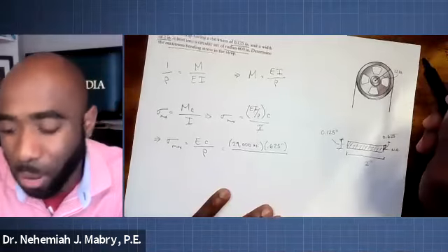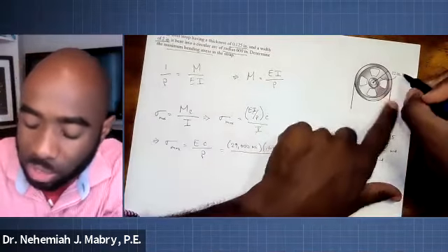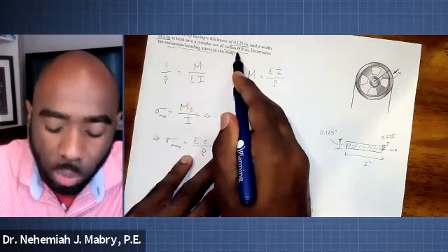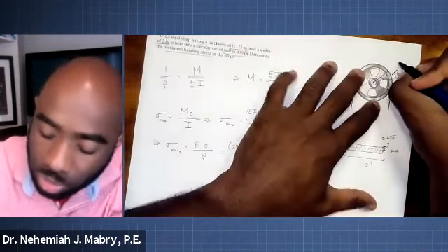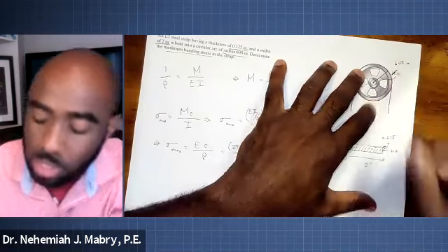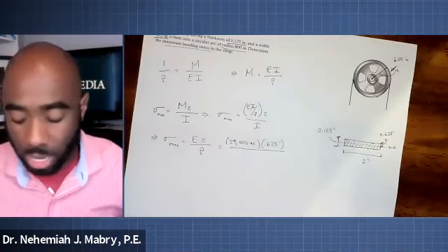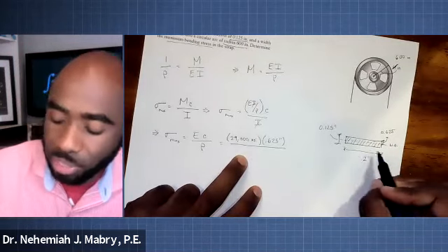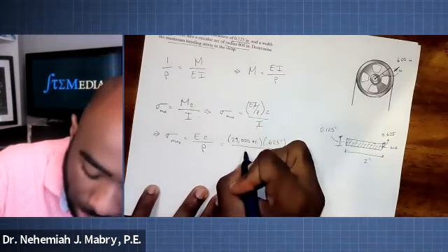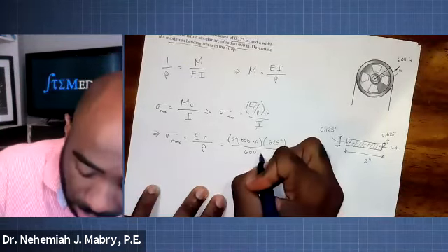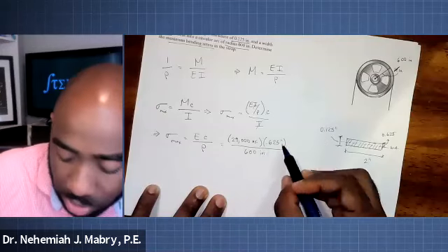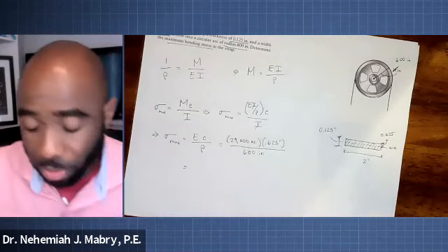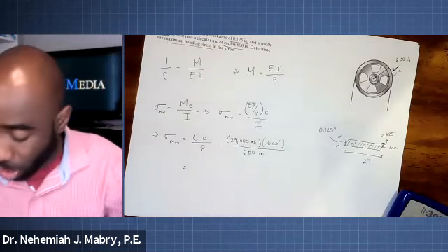Now, they made an error in the book for this particular problem, and they put 12 inches there. So don't let that throw you off. It says in the problem that the circular arc has a radius of 600 inches. So instead of 12 inches, that should be 600 inches. That is definitely an error in the diagram. So rho, in this case, the radius of curvature of this particular steel strap, is 600 inches. So now we have 600 inches, 0.625 inches, 29,000 KSI. And we can do the math on that right away to solve for our maximum bending stress.